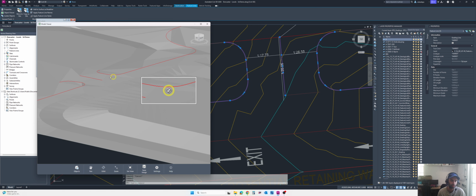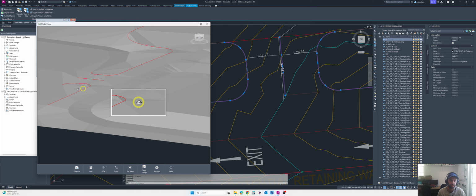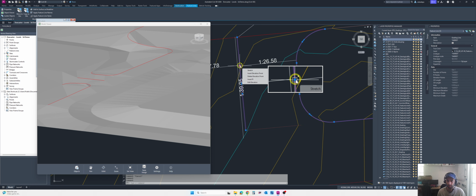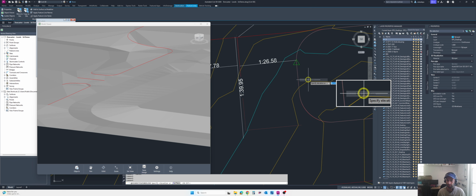This one is a bit up and this is down, so we can lower this one maybe to match. This one is 38.392, and then let's also change it with edit elevation to 38.292, or maybe just 38.392 will also work.